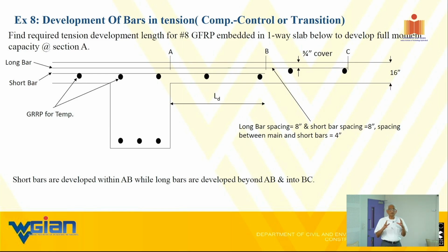So my message is confinement through wrapping or confinement through this type of a hinge formation between the reinforcements and the stirrups will give you this kind of confinement easily, will increase at least the ultimate load by a factor of 2. Ultimate load, I said, not necessarily the initial crack load. But on the other hand, if you wrap it externally, even the initial crack load will go up 2 to 3 times. Of course, that all depends on how many wraps you have, what is the stiffness of the wrap versus the core material, and so on. We know that.